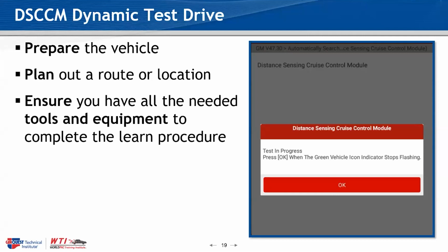Everything you're seeing feedback-wise, all the data that's used and acquired, all the radar sensing technology that's happening is all done in the module. You're just sitting there receiving data back. So something to think about when you start talking about aftermarket scan tools is will they work, will they not work? I don't know. I know that the OE scan tool will work, and I confirmed in this one instance, on this one vehicle, with this one version of aftermarket software, this one time, that it did function. Was that good enough, Jim?